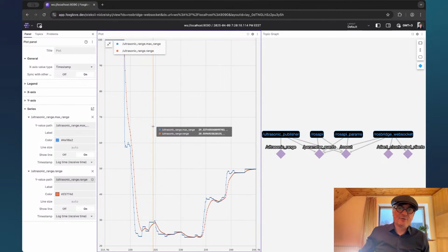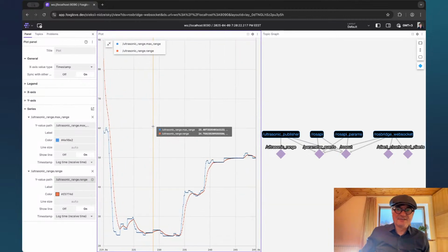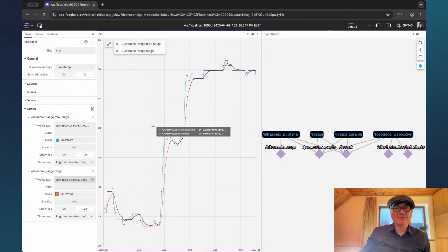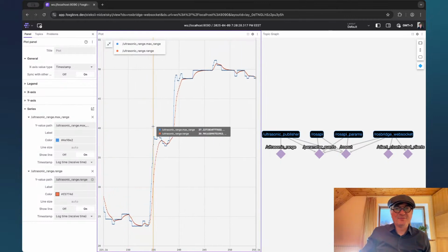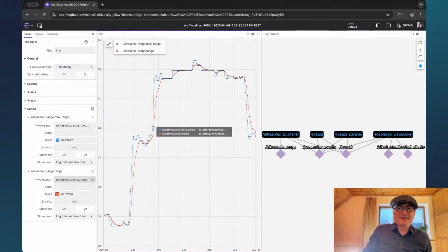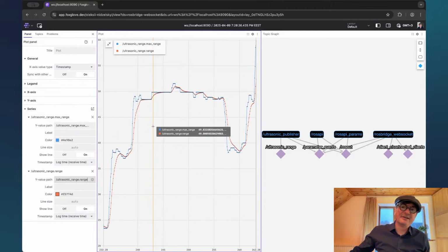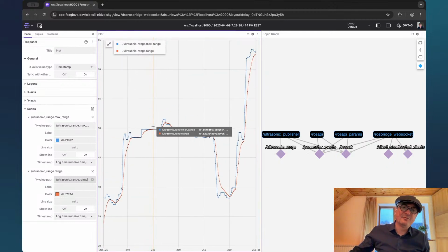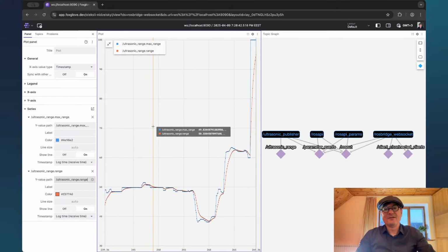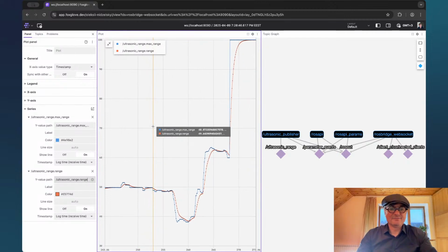So this is a great tool to visualize what kind of data we receive from different sensors, for example from the ultrasonic sensor. Now it is approximately 50 centimeters. It can be decreased if I move the obstacle closer, and increased if I move far away from the robot. So in this way we can control our data.